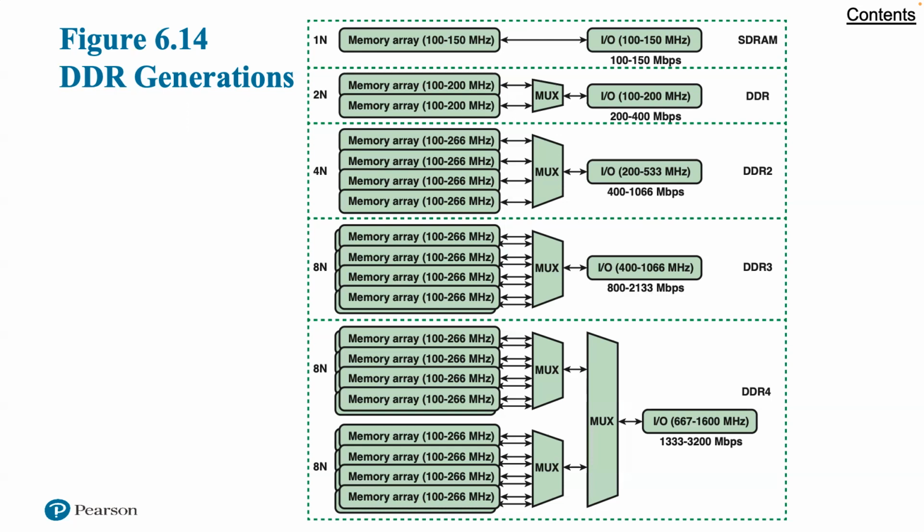Although each new generation of SDRAM results in much greater capacity, the core speed of the SDRAM has not changed significantly from generation to generation. To achieve greater data rates than those afforded by the rather modest increase in SDRAM clock rates, JEDEC increased the buffer size. For DDR2, a 4-bit buffer is used, allowing for words to be transferred in parallel, increasing the effective data rates by a factor of 4. For DDR3, an 8-bit buffer is used and a factor of 8 speedup is achieved.